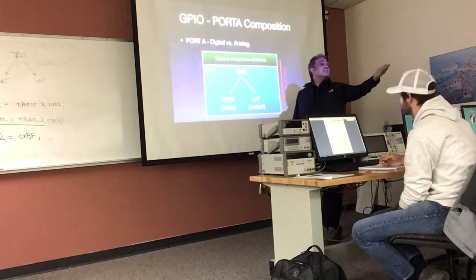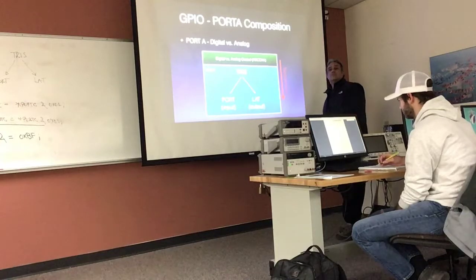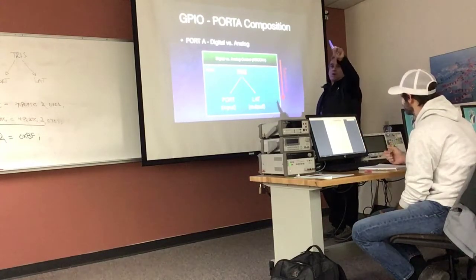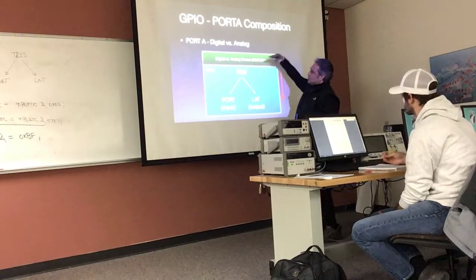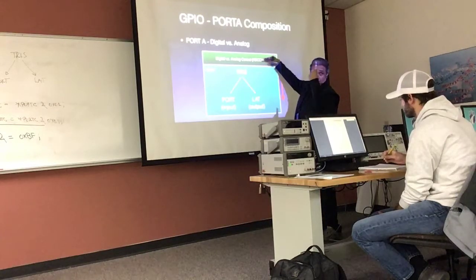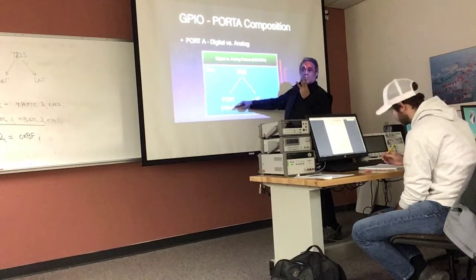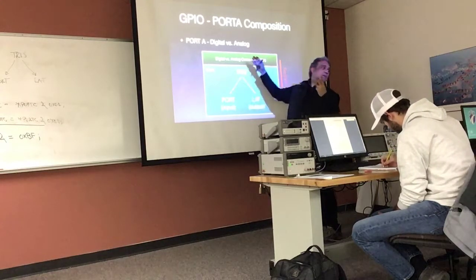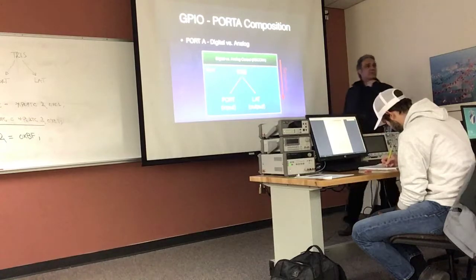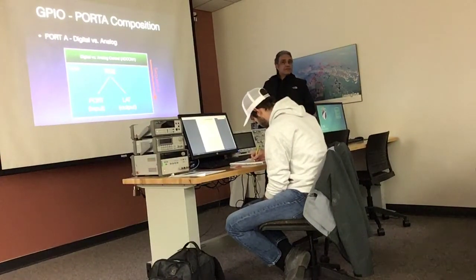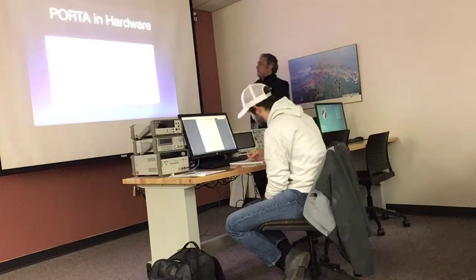So what's going to happen in software, the reason why I call these software considerations, is that you're going to have 3 instructions to manipulate one pin. You're going to have to control the ADCON first, control the tris, then use the port. And it has to follow this sequence. Without that sequence, it will not work. At least it will not make any sense. Any questions?